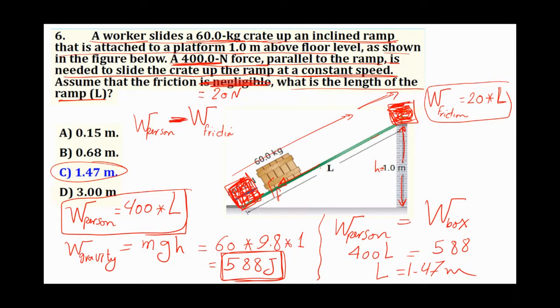Some people can consider it minus while they calculate the friction, or they can add the minus as I did now. Minus the work that is lost by the friction, the leftover is given to the box. The leftover is the work given to the box.